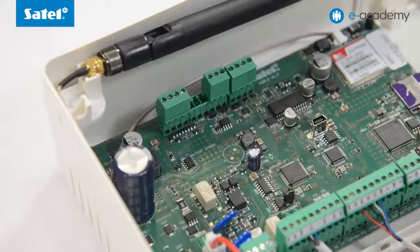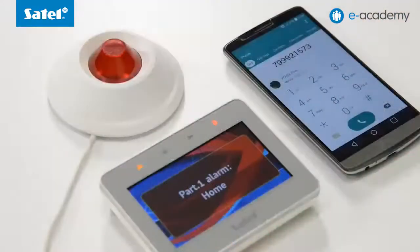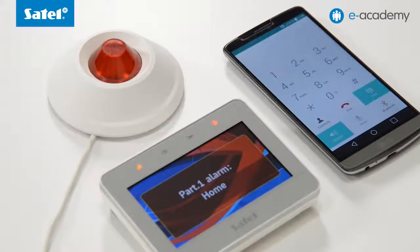Before setting up connection with the control panel, we will trigger the Tamper Alarm so as to demonstrate full functionality of the voice menu. Now let's proceed to establish audio connection with the control panel. Dial on the smartphone the number of the SIM card installed in the control panel. The control panel receives the call and plays back the welcome message defined in the previous episode.